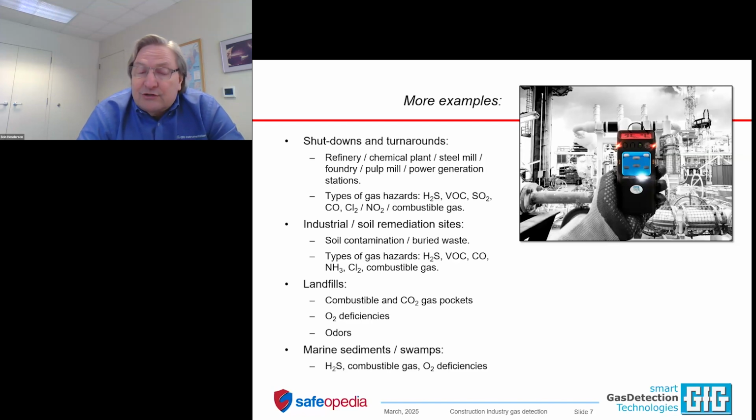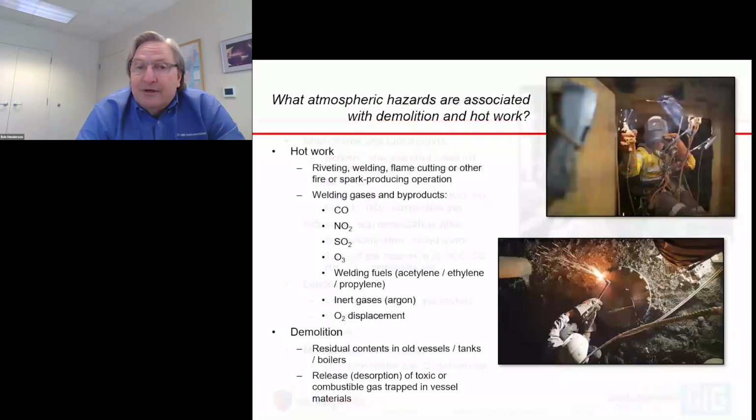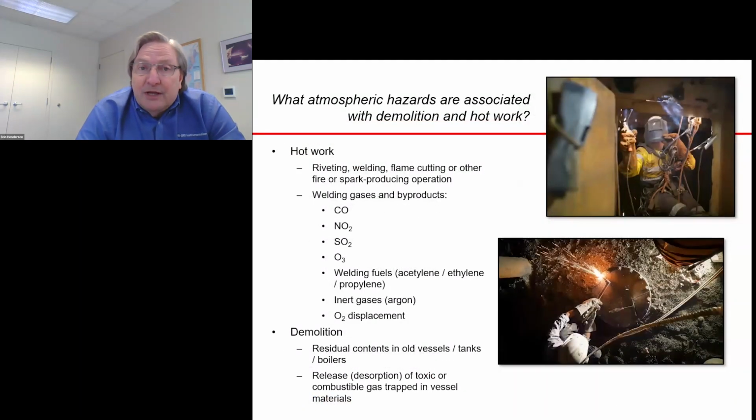Landfills, a lot of new construction is on landfills where you have combustible gas, CO2, pocketing. You need to be very vigilant and especially careful with your gas detection when you're building on a landfill. Marine sediments and swamps, again, same thing. You have H2S, combustible gas, heightened likelihood of oxygen deficiency that can occur in pits and trenches through the marine sediments. So keep on your toes.